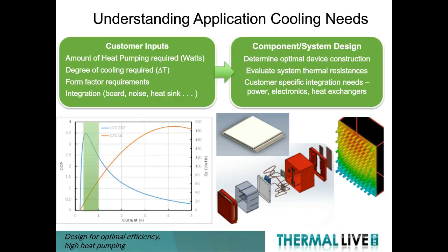So it's important to drive these appropriately, best with a direct DC outputted signal. And that allows you to more dynamically control the capacity, as well as make sure that you are not inadvertently running the system outside of its design envelope simply because of the way you provide power to the system.